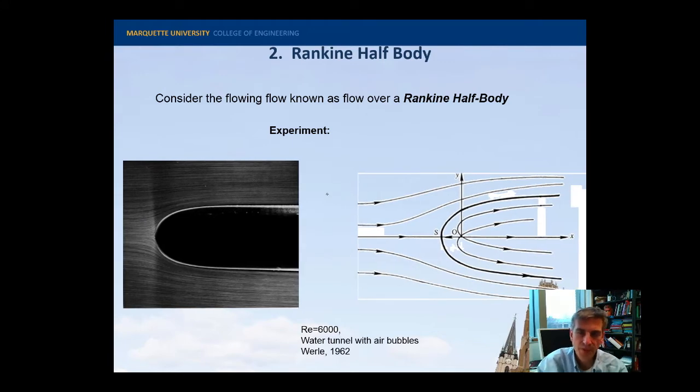Now, something important to keep in mind is that this is the flow solution that we get from the irrotational flow solution, right? And so you've got these streamlines, and they look something like these streamlines here, and that's all great. But what about what's going on inside the body? Well, remember, this whole thing is the flow solution for the free stream plus a point source.